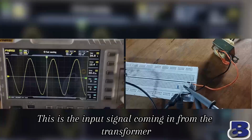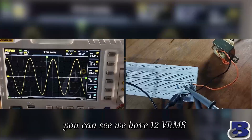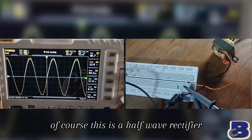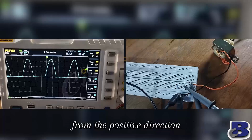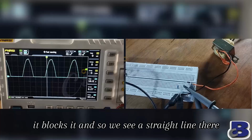This is the input signal coming in from the transformer. You can see we have 12 VRMS and 35 peak-to-peak volts. So if we look at the output of the diode, of course this is a half-wave rectifier. If we look at the output, we see we have the negative part of the waves cut off, so the diode allows current to flow from the positive direction. And once the current is about to change direction, it blocks it, and so we see a straight line there.